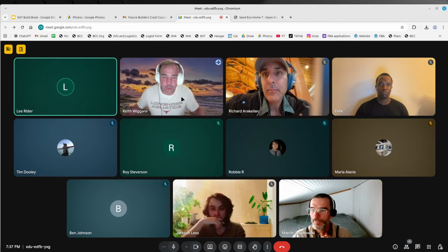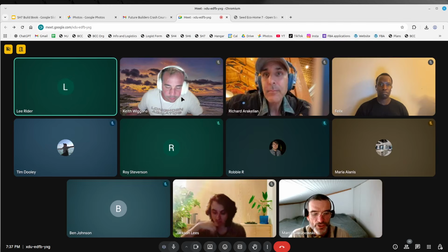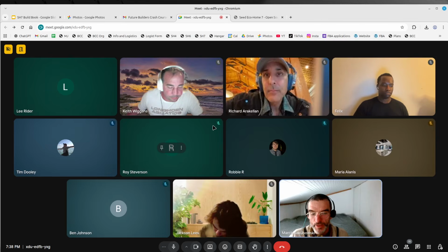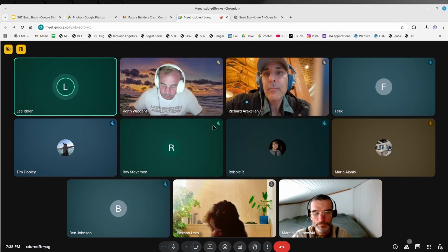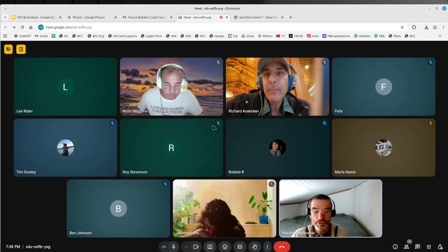Marcin, go ahead. I was going to ask, with that gravel you put on the roof, are you adhering that somehow? No, it's locked in mechanically. That's just pea gravel, round river rock, the small quarter inch. There's a mesh at the gutter side that holds the gravel in, so the water goes through and the mesh holds the gravel. You don't have to worry about heavy rain moving it around, leaving spots exposed as time goes on. I don't think so. I haven't seen that, at least on the roof for this house we sold in Maysville. That's intact.